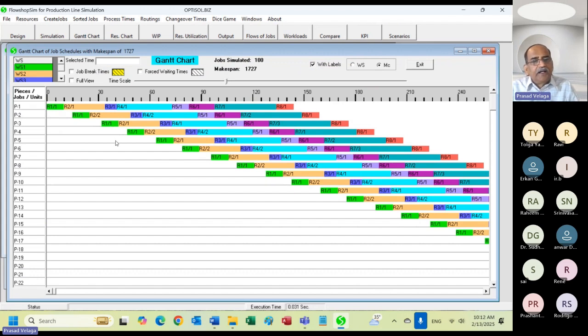Here you see, when I run a different algorithm, it releases the pieces to the first workstation at the right time. But it doesn't keep the first one busy all the time. But every piece flows through the system without any waiting at all. Though the cycle times are different, and the number of machines varies with the work center, still we can release every piece at the right time so that you achieve one piece flow. I wanted to show you that.